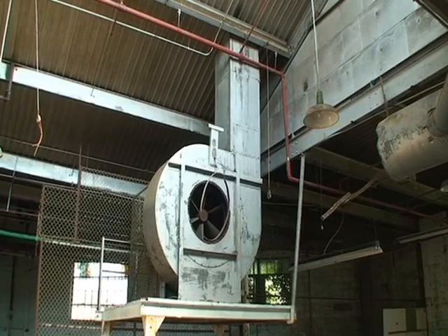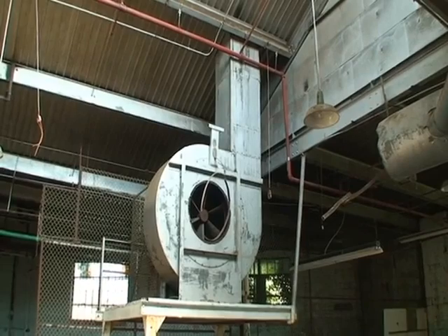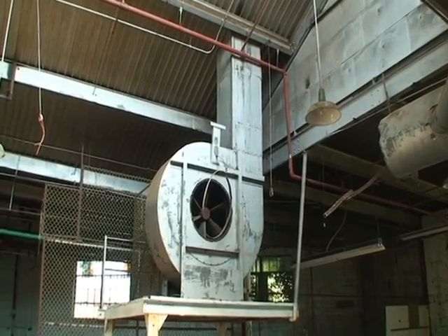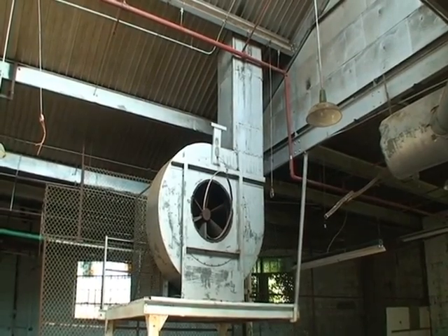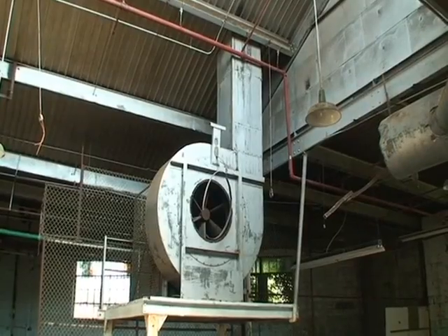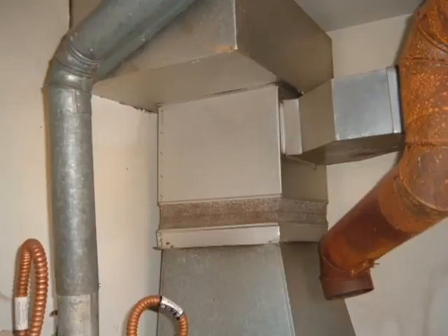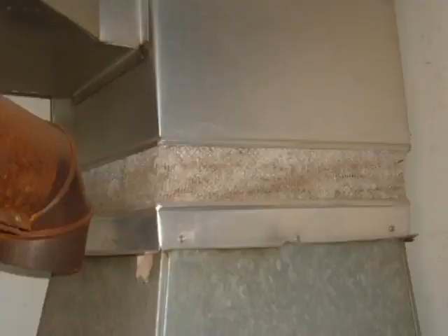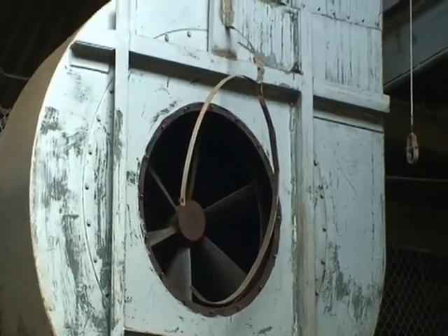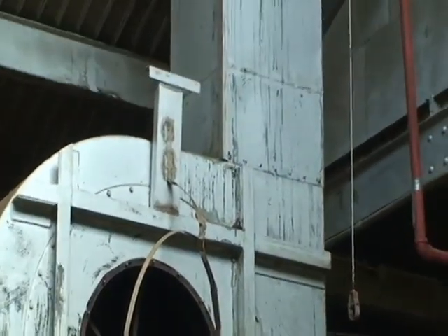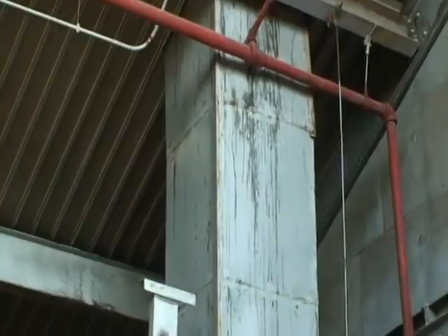Here's an example of a fan unit. While this particular unit doesn't have it, it's not uncommon to find on the exhaust side of this fan a piece of flexible duct dampener in between the actual fan unit itself and the duct that it connects to. That dampener is in there to take vibrations out of the duct when the fan's running. Usually that cloth would be considered a Category 2 non-friable unregulated material when it's new out of the box. Unfortunately, over time it will tend to deteriorate and should probably be handled as a regulated material when it's removed.